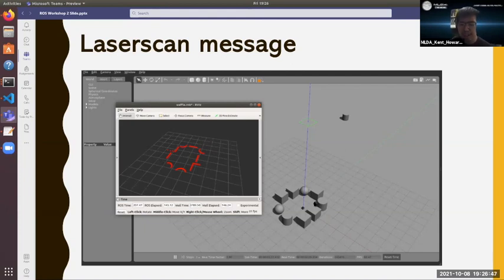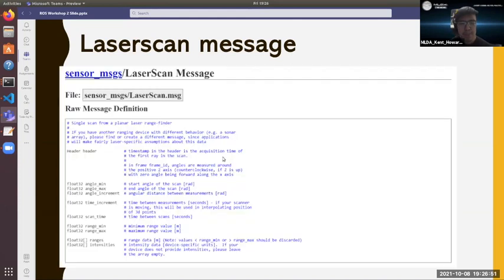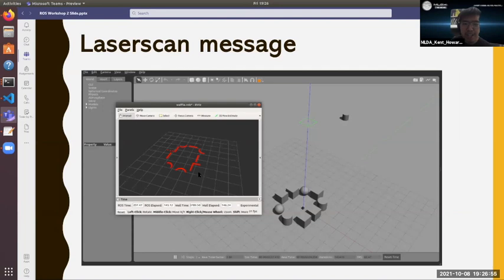laser scan is received. Actually, you can see the configuration I made here. So that's the concept of angle min and angle max. Angle min is the starting angle, and angle max is the ending angle, if I have to explain so crudely. So you start with angle min. Let's say your minimum angle is minus 3.14, then it's facing the negative direction, and it pokes one, until you hit the angle max.